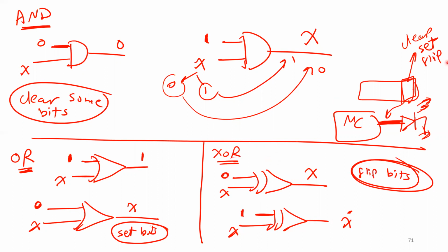So if I want to flip this bit, all I have to do is an XOR operation. I am going to put 1 here and 0 everywhere else, because with 0 I'm not going to change those bits, and I only want to manipulate this bit. Very interesting. When you flip a bit, that's what we're going to do in the next chapter. If you want to make a flashing LED, flashing means you turn it on for some time, off, on, off, on, off. To do a flashing LED, all we can do, for example, is flip this bit every 1 second, using this idea.